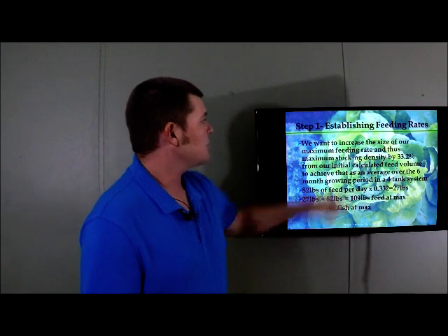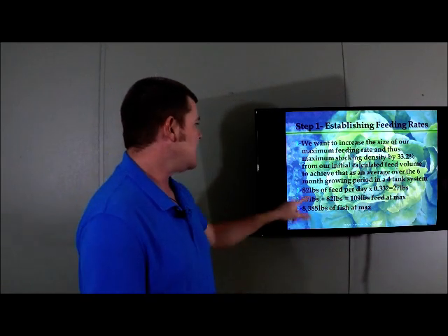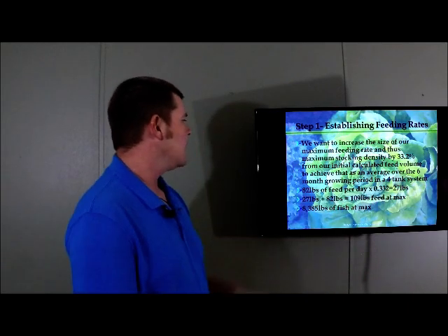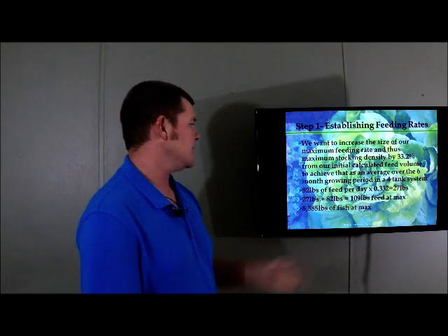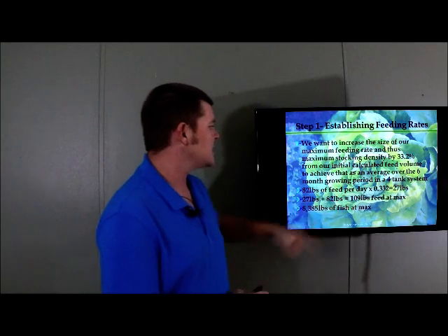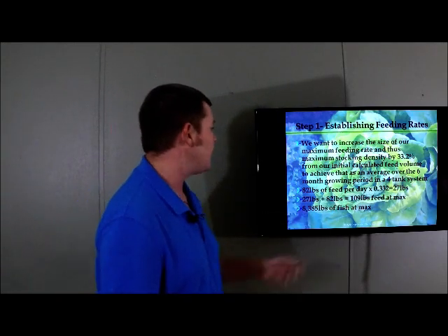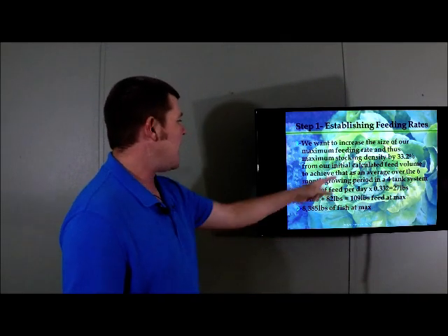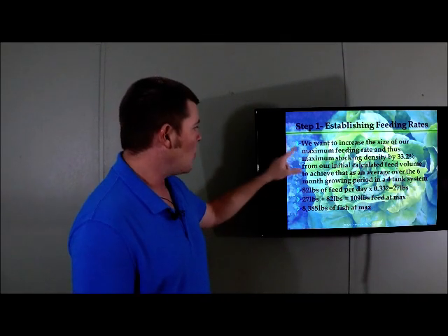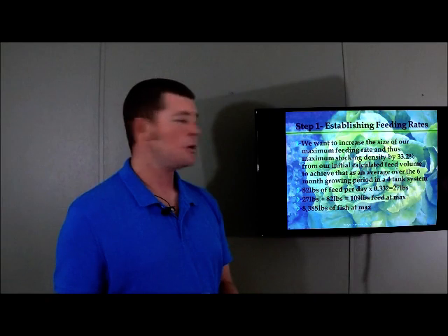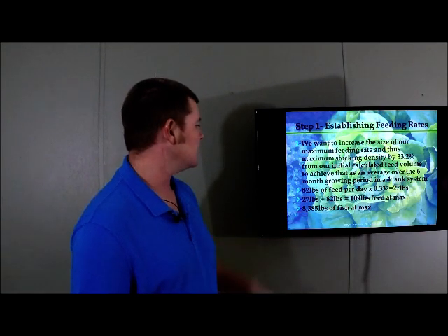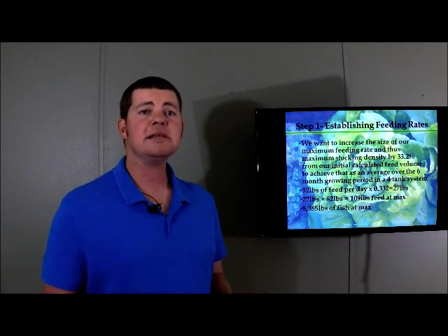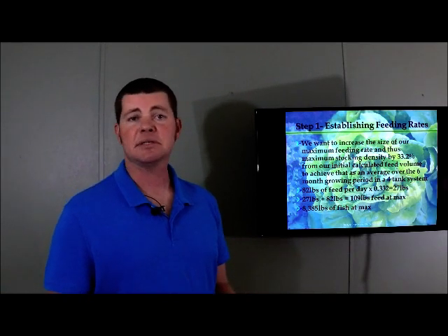So if we multiply 33.2% times our 82 pounds of feed, we get 27 pounds of feed. Add that back to the 82 pounds, and now we get our true maximum feed rate that we need to design around. And that's 109 pounds of feed per day. That relates back to fish at the 1.3% feeding rate per day. And it gives us 8,385 pounds of fish at a max. So we're already getting real hard numbers that we can design around.